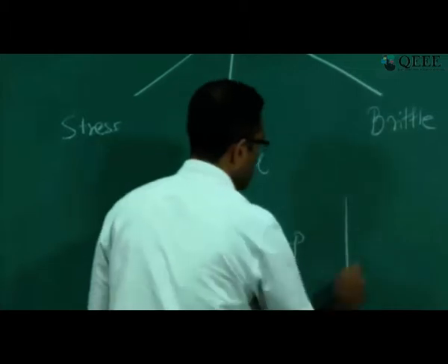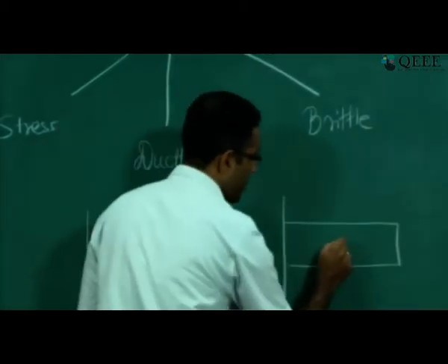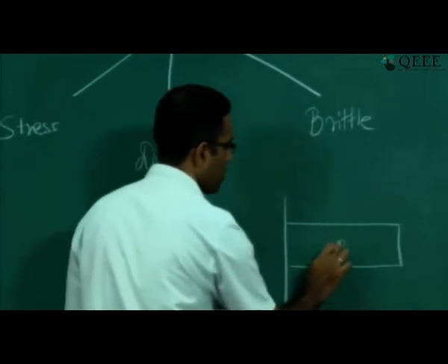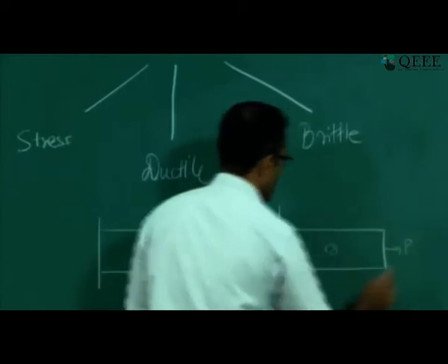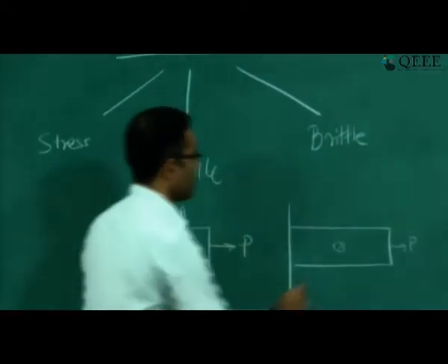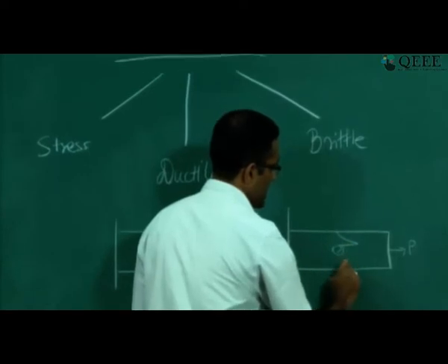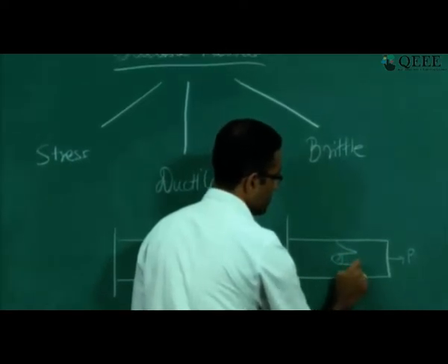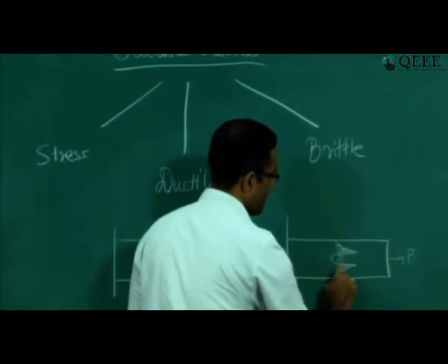But at the same time, if you have the same bar, but in this bar you have provided some sort of a hole, say for example you wanted to put some screw there, now if you subject it to the same P, then the stresses in the vicinity of this hole are going to be very high. Okay, the stress distributions are going to be slightly different.